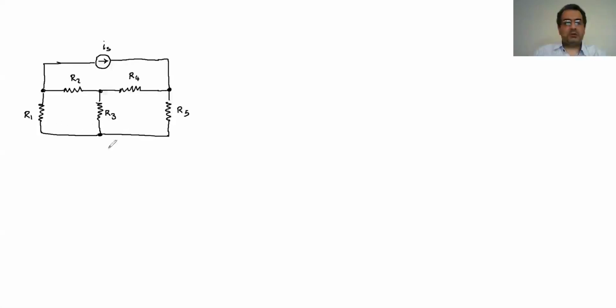If not, try to choose the one at the very lower end. Otherwise, don't worry about it. The only thing is that when you write the voltage equations, you consider the voltage at that node to be 0. So it doesn't matter which one I choose as a reference, but just to follow the books, I choose this one.